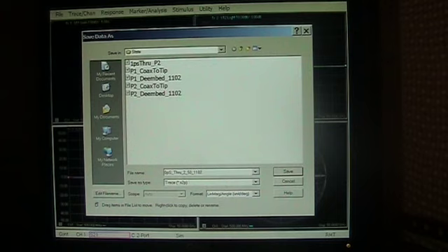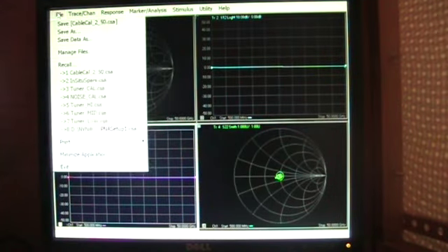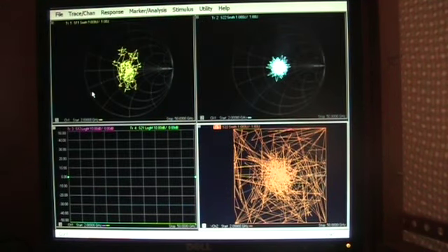And remember that the measurement is going from left to right, and so if we were to use this as a de-embed, we now would actually have to tell it to reverse the adapter ports. We'll go ahead and save this. We've got today's date on it so we don't lose track of it. And now what I'd like to do is go over to the tuner calibration, if you remember this, and we have 2 channels that we need to set this up on.